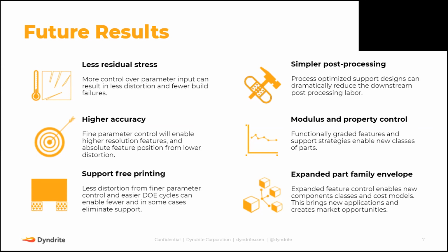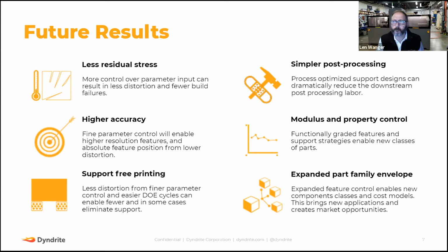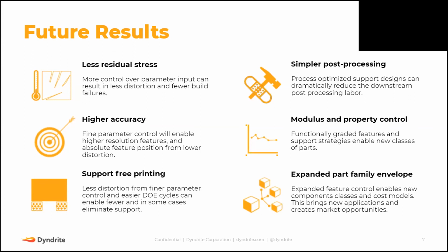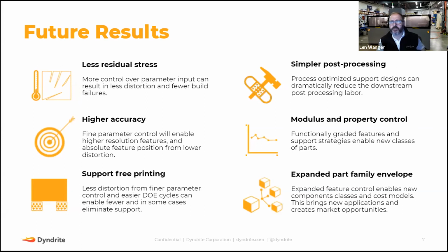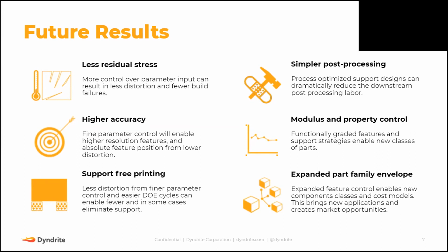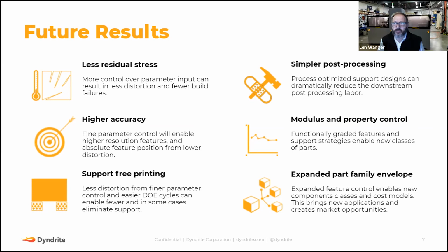I'd say, Len, to cap my set of questions, zoning in your process is going to be obviously very different than a powder bed fusion process. For example, you mentioned the blooming and the filtering. What other types of geometric queries would be useful to you beyond upskin, downskin, inskin, and the border? Yeah, so there are two I'm thinking of. One is the ability to set a camera point and do a ray cast to find a distance to intersection with the model. If I get that, it dramatically helps with being able to do smart cleaning of my objects.